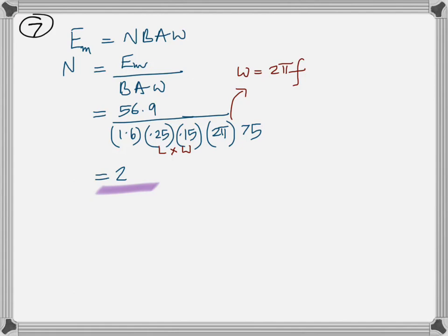Now can you tell me this? What would be the current at that time? The applied EMF is 125, the back EMF is 105. So the voltage is only 15, right? And so 15 divided by 6 would give you, how much is that? 2.5? Come on. 2.5 amps would be the current through the motor at that time. That make sense?